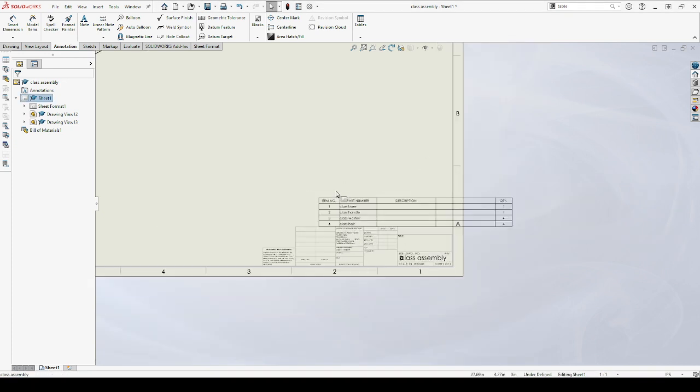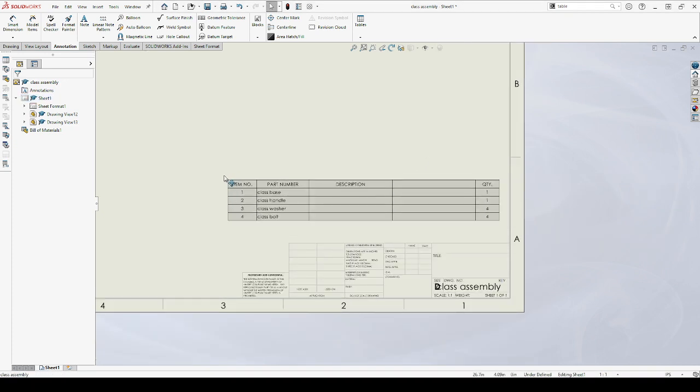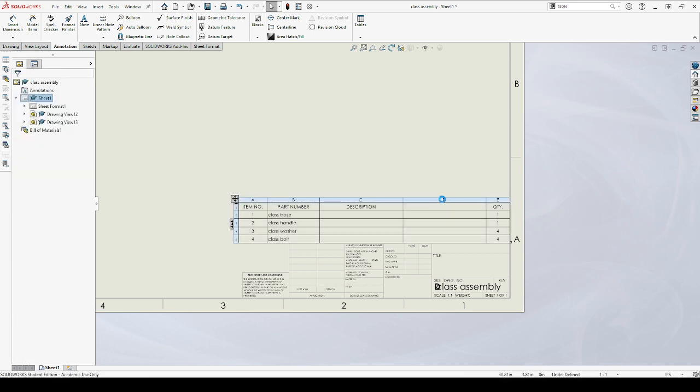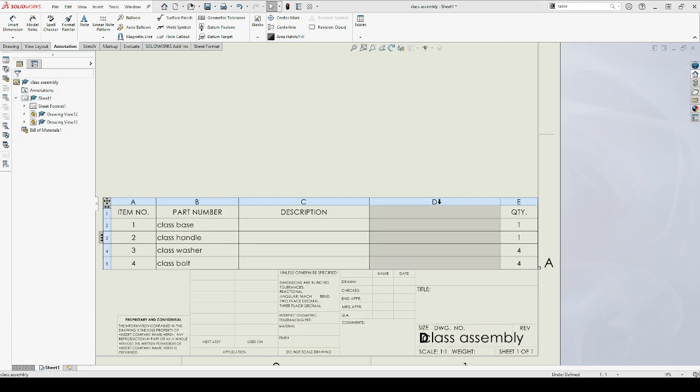I'm actually going to move this over first before I do that. Then I'll come over to my column, click on it, go to column property, and click on it there. It's currently not set, but I can set it to the new one that I just added, the material. Or I can change this custom property to something that's already available. But I did make a new custom property, a material, so I'll set that. And then boom, now I have material here and I have copper there.